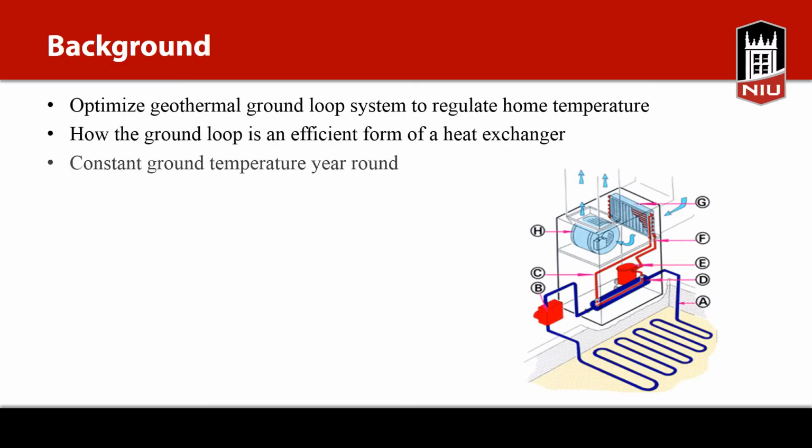The purpose of the research conducted was to design an optimal geothermal cooling system for a generic house. Geothermal heat exchangers are a form of thermal regulation which rely on the environment rather than fossil fuel. A geothermal heat exchanger works by running water underground, which maintains a constant temperature of 50 degrees Fahrenheit in the Midwest. This allows water to either be heated or cooled in a secondary heat exchanger system and brought back to the neutral temperature of 50 degrees Fahrenheit for only the cost of pumping.